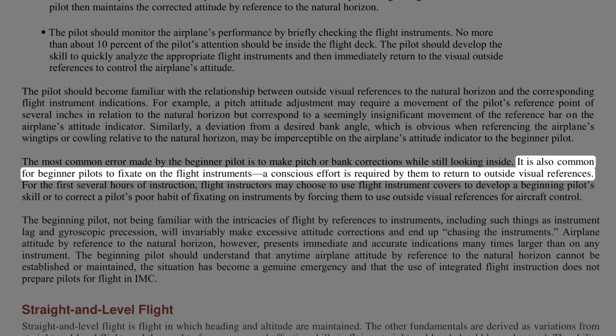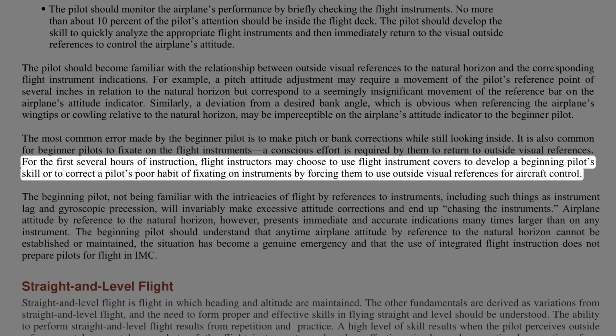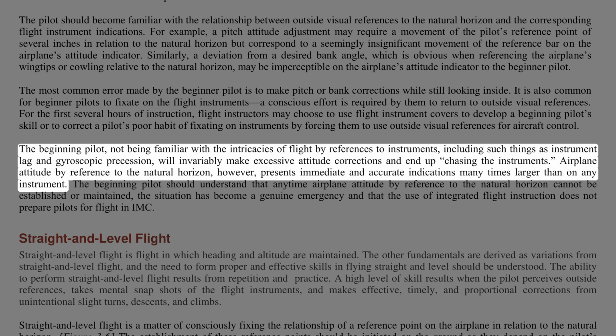The most common error made by the beginner pilot is to make pitch or bank corrections while still looking inside. It is also common for beginner pilots to fixate on the flight instruments. A conscious effort is required by them to return to outside visual references. For the first several hours of instruction, flight instructors may choose to use flight instrument covers to develop a beginning pilot's skill or to correct a pilot's poor habit of fixating on instruments by forcing them to use outside visual references for aircraft control.